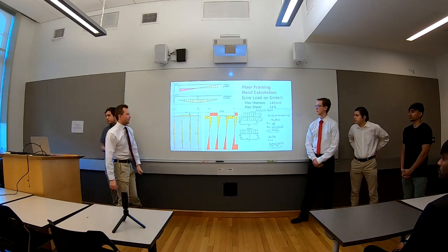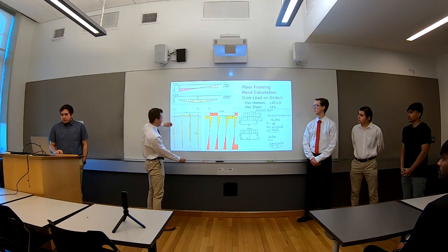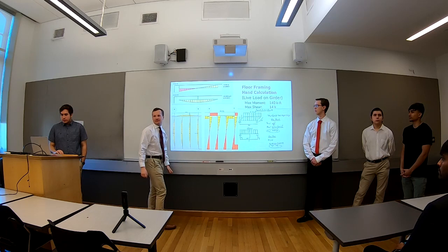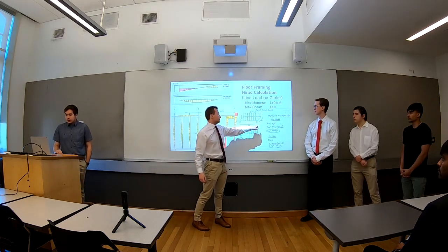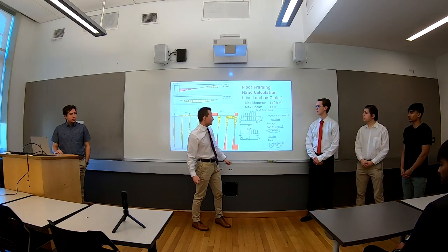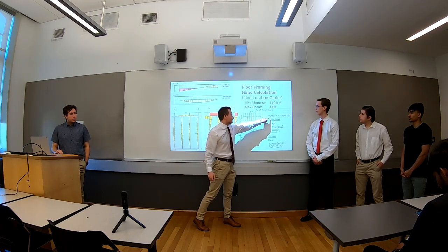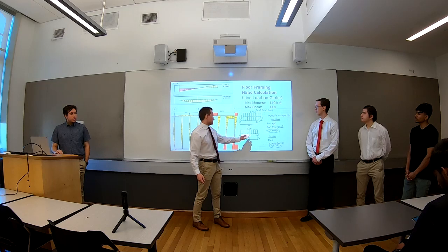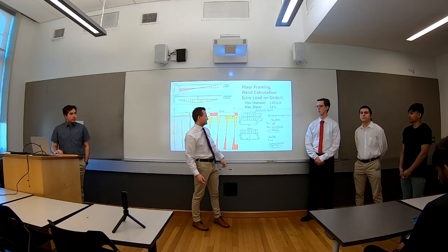Alright, so here we have a sample calculation for a live load. We decided to do the sample calculation with this girder right here. It's in between one of the 30 by 40 sections that we had in our floor plan. First off, we found the tributary width to be 10 feet, and we used a live load of 70 pounds per square foot. Then we had to make it a two-dimensional calculation, so we multiplied 70 PSF by 10 feet to get 700 pounds per foot. I converted it to 0.7 kips per foot to make the calculations a little bit smaller.